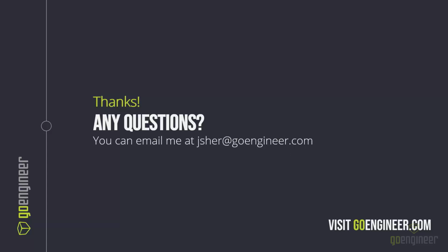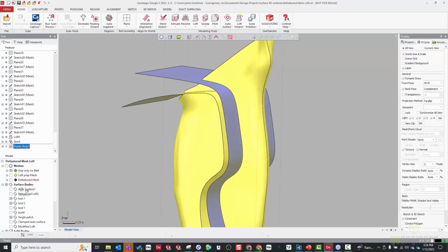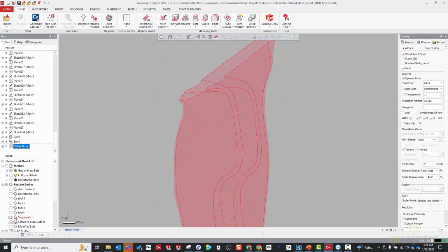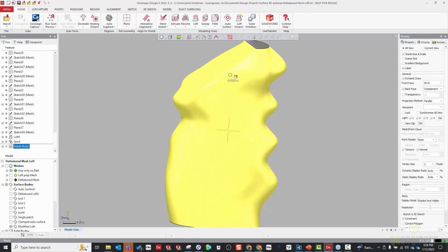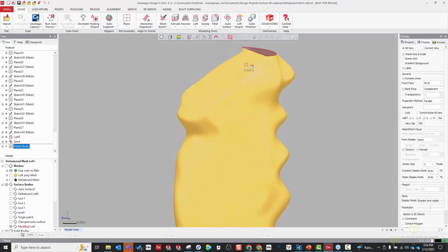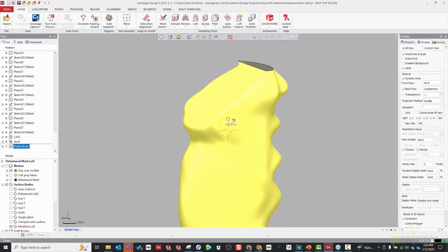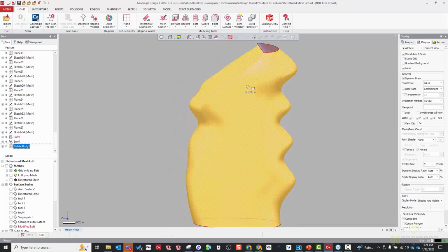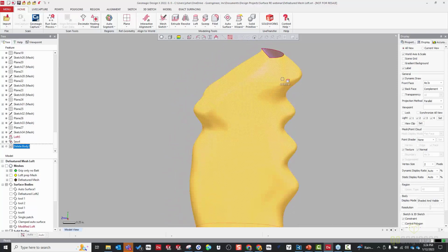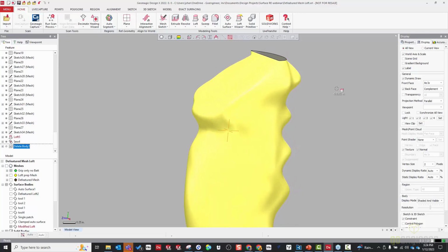Dan, great question. So Dan asked, any reason you can't close the sections manually instead of having to close the surface? No. So you can absolutely go in and close each. So when he's talking about the lofting operation for creating surfaces, and instead of closing off this area in the mesh, leave it open, and then when you create your cross sections, just add some lines to close them off that way.